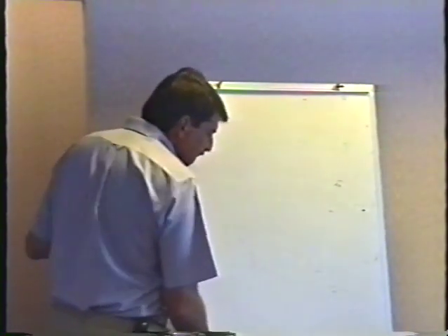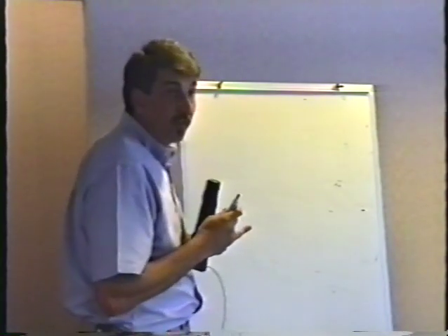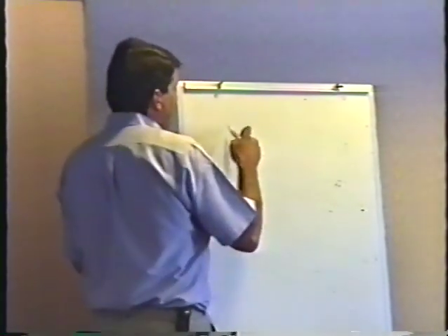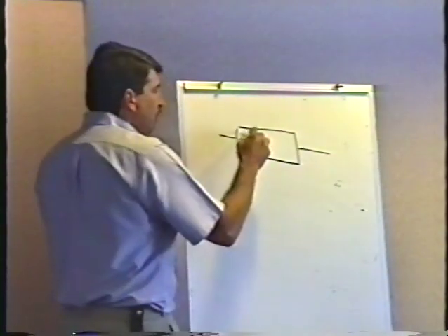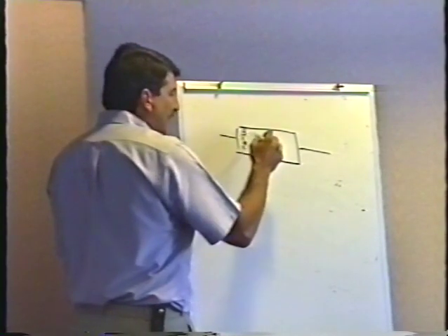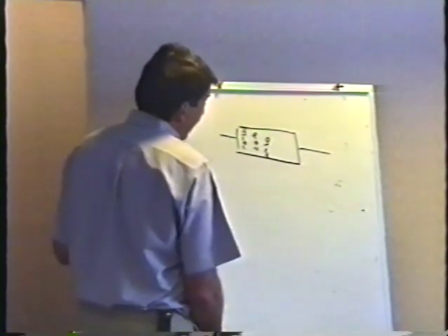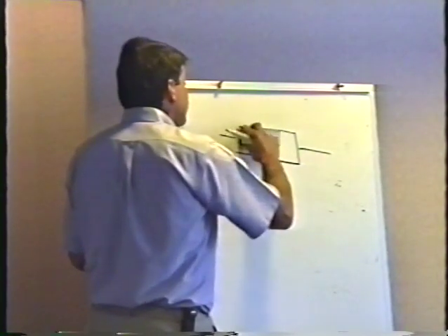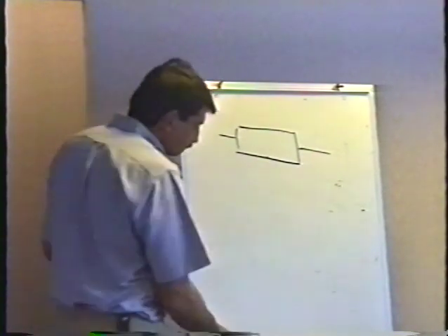The first band of a resistor is never black. That is, it's never 0. You would think that if we wanted a resistor that was 1 ohm, it would be black, brown, black, wouldn't you? But it's not. For some reason, I have no idea why, the first band is always brown or higher. That is, it's always 1 or more.